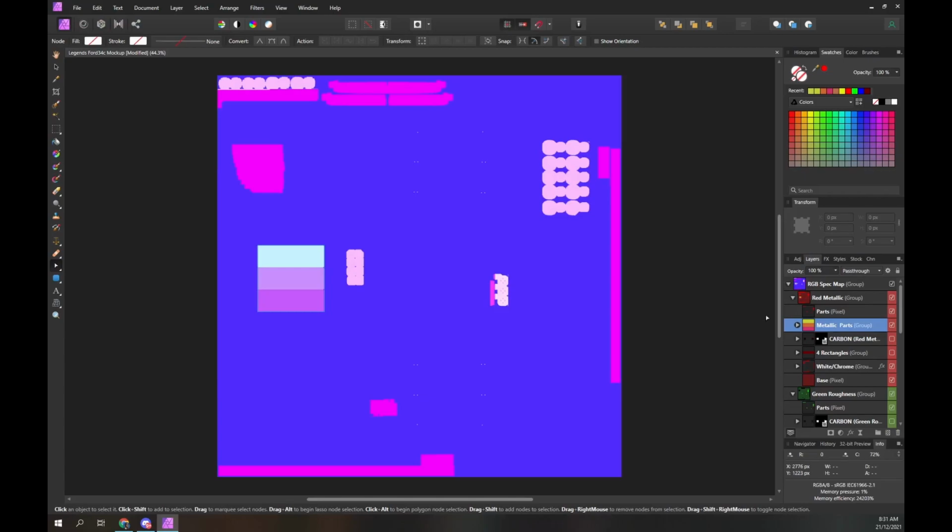There are many ways to change the color of our parts to red and green spec map values. We could simply flood fill color into these parts. You may need to do it that way in some programs. If you flood fill red 32, green 0 and blue 0, that's a low shine or metallic effect. If you flood fill red 180, green 0 and blue 0, that's a high shine and metallic effect.